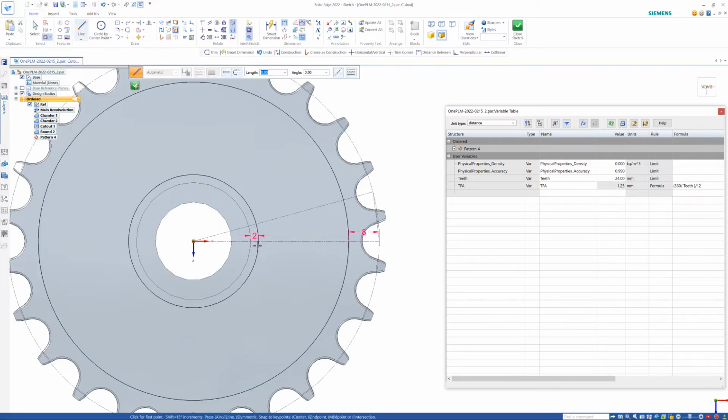Okay, I'm then going to do 2 lines coming from there to create a segment. I'm going to connect the line to the origin point, and the same with this one. I want to do a horizontal and vertical between, could do the midpoints of the lines actually, that'll probably work fine. And we can do an angle constraint between these lines. So smart dimension, A key, so the second line.